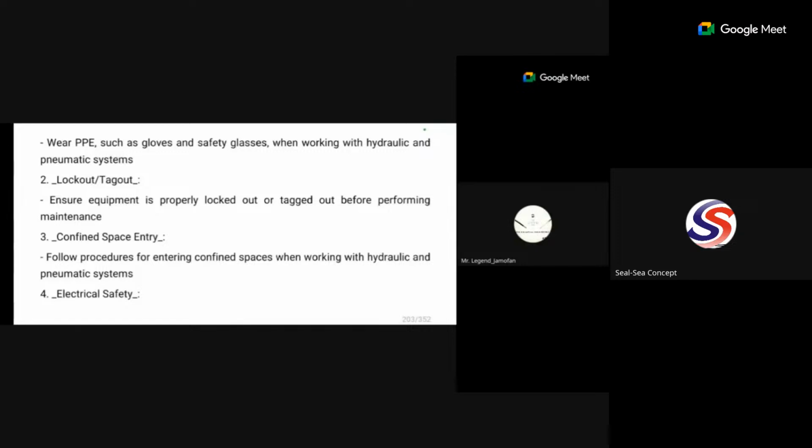If they drag the chain and there's no response, they have to drag him out because it's a confined space. Sometimes people go in with additional oxygen to breathe. Sometimes they have to do air testing there, for example if they are performing welding work, to know if there could be a fire outbreak or anything like that.